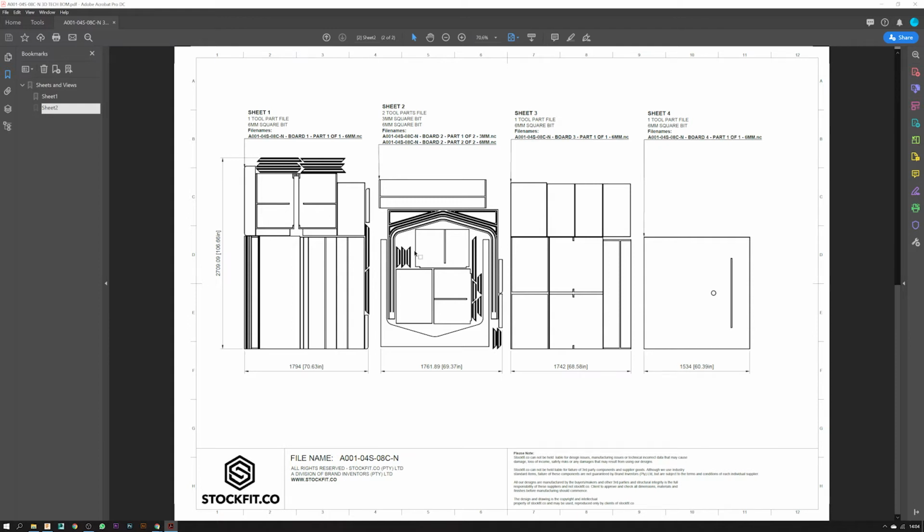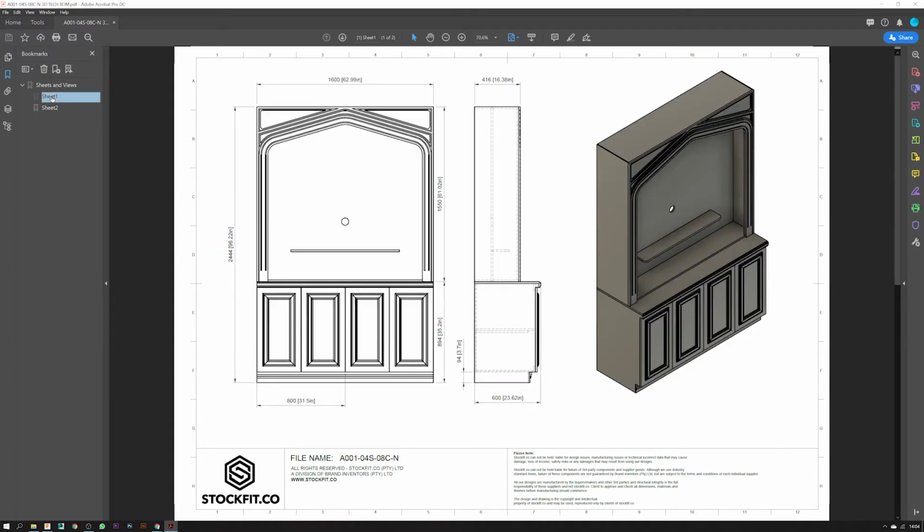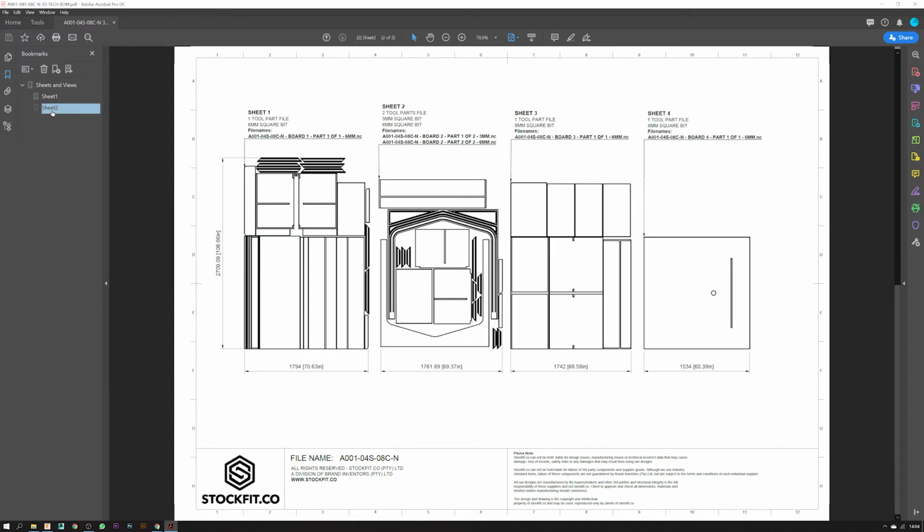In the end, we've tried a couple of different nesting profiles, and this is what worked out best because of the size of the panels. So that is basically the normal technical and bill of materials. You'll need 4 sheets of 16mm, you'll need a 3mm and a 6mm bit, and off you go. You've got 5 G-code files that you can simply load on the machine and then run. And these are the panels as you would get them out of the machine. So that's the first part.